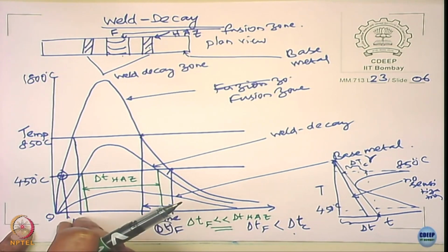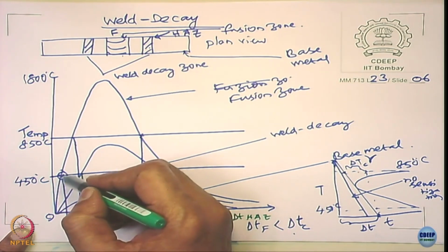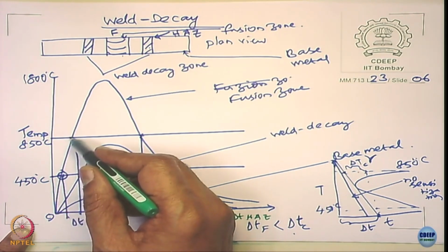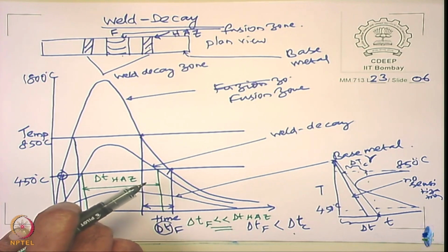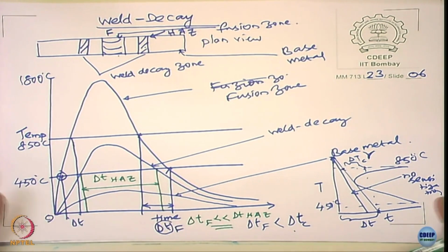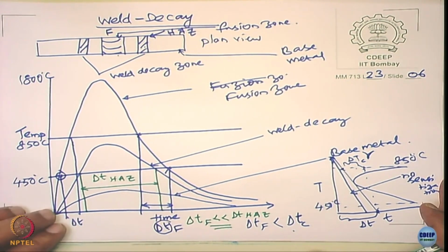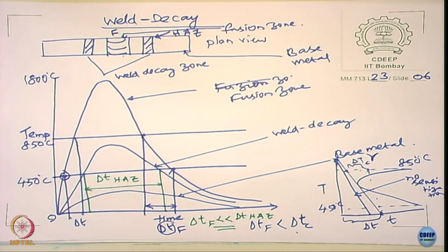This is the thing that you should be looking at. What is the thickness of this delta T? It only says that when you weld it, the fusion zone goes through the sensitization regime from 450 to 850 for this much time, okay. It may not sensitize, even it sensitizes, assume that if this delta T is much larger, even then what will happen? Because it goes through higher temperature, that will get dissolved, the chromium carbide get dissolved.